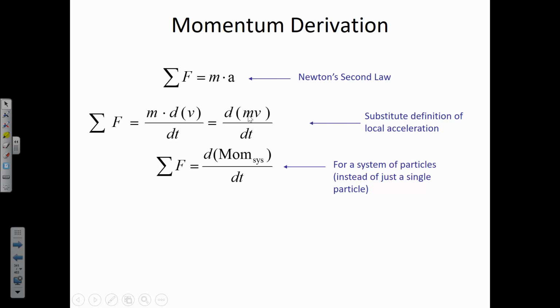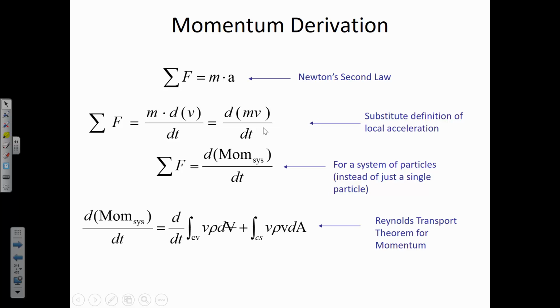But in order to generate the thrust, the strategy was to maximize the velocity, because the mass flow rate itself was limited by the fuel available. That same factor is true in most aircraft, where they're trying to reduce how much fuel has to be carried up in the plane, so they make the jet engines maximize the velocity in order to get as much force as possible.